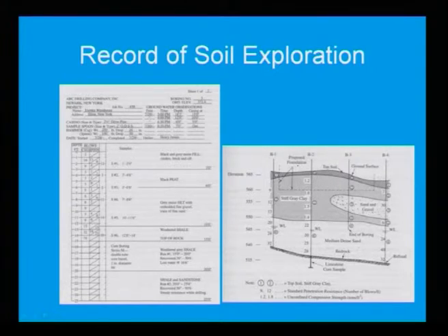If you look at here, steep grey clay, it is up to 550 elevation here, and borehole 2 is also 550 elevation, same soil is there, fine. Now, the moment you go to borehole 3 and borehole 4, look at here, the steep grey clay is there up to 560 of your elevation, then between 560 to 550 sand gravels are available. Look at how the profile is varying.